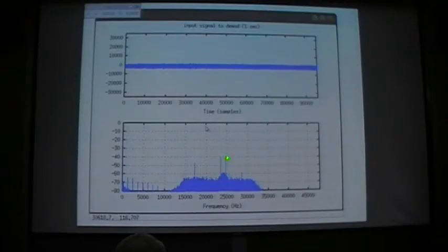Now in the middle here, you can see these two tones sticking up. This was a 2FSK signal, so 2 frequency shift keying. So those two tones are, I can't remember if this is 1200 or 2400 apart, but it looks like about 1200. So they're your two tones, your 1 and your 0, coming through the signal there. And that was high enough to be received at, I think, about 1% bit error rate as a minimum detectable signal. And that's sort of how we debug. There's some things we can do with the analog test equipment, like the spec analyzer and signal generator, and other things we have to look at what the microcontroller is seeing.